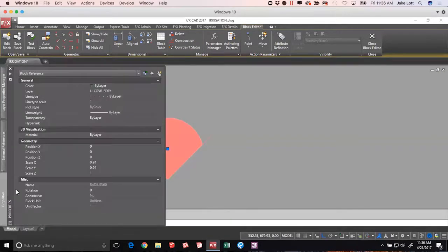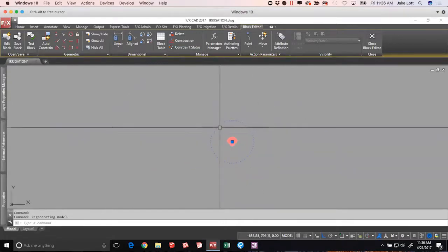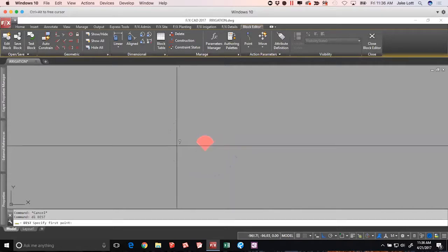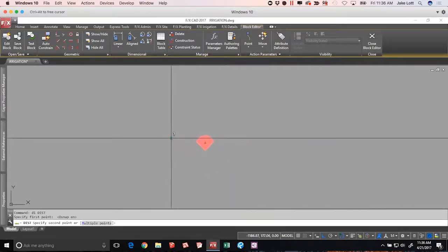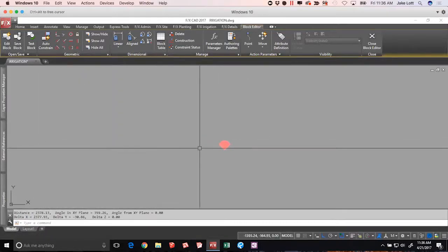Being able to go into properties and view its scale, that scale is just super off for what it needs to be. So again, scale it by a reference of a length, or I'm just going to scale him up to 1200 here. And you're going to see that now he's back up to this realm here. And if we were to do a distance on this guy, just like that, he's closer to about 4 feet, which is probably right.